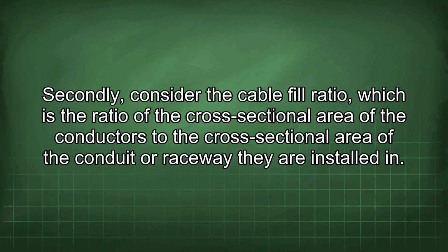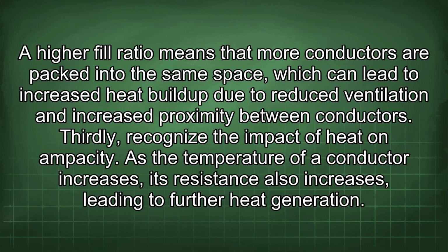Secondly, consider the cable fill ratio, which is the ratio of the cross-sectional area of the conductors to the cross-sectional area of the conduit or raceway they are installed in. A higher fill ratio means that more conductors are packed into the same space, which can lead to increased heat buildup due to reduced ventilation and increased proximity between conductors.